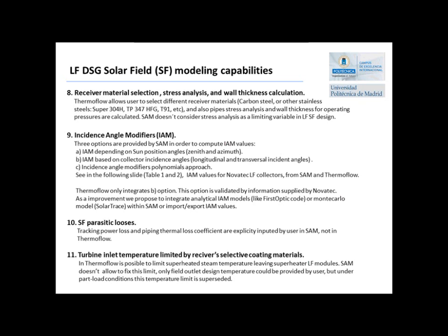Turbine inlet temperature limit by receiver selective coating material. In Thermoflow, it's possible to limit the superheated steam temperature leaving the superheated LF modules. SAM doesn't allow fixing this limit. Only the field outlet design temperature could be provided by the user as a reference, but under part load conditions, this temperature limit is superseded.